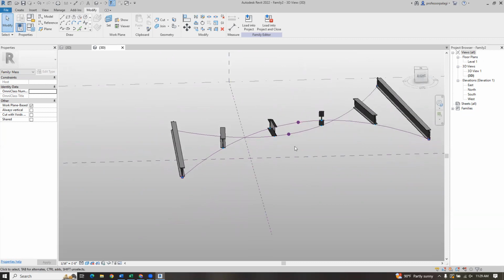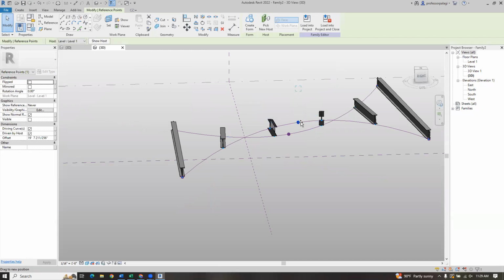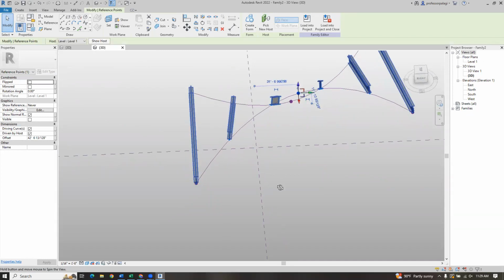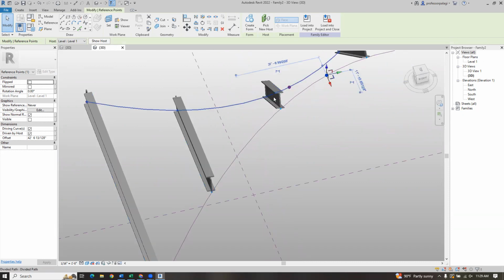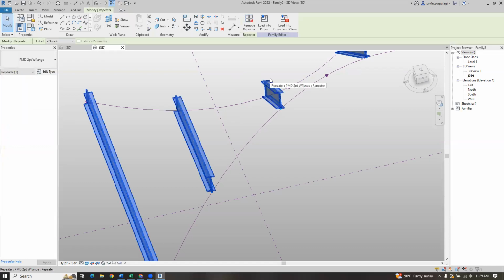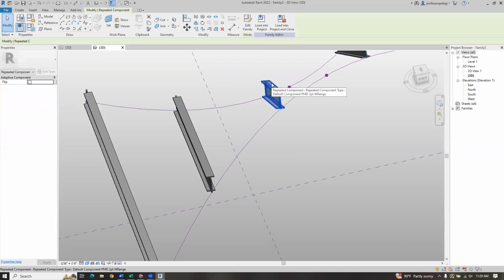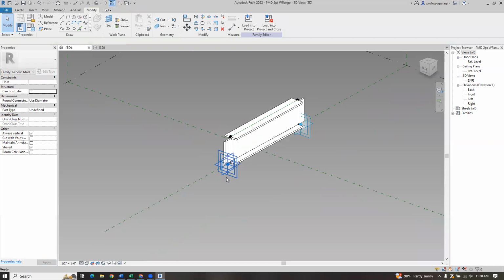Now, there are times where you might want it to be perpendicular to the surface. Let's say this one right here is not perpendicular to the surface, it's vertical, right? Makes sense. But sometimes, if it's a curve, I want it to roll with the curve in a way, right? So let's go back in and, if you don't have it open, tab in.